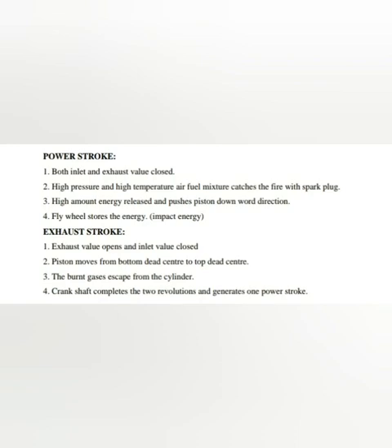In the next cycle, the piston starts moving from TDC to BDC, the inlet valve opens, allowing the charge to enter the cylinder, and the process continues. Thus, the four different strokes, or one working cycle, are completed when the crankshaft rotates through 720 degrees, or 2 revolutions of the crankshaft.